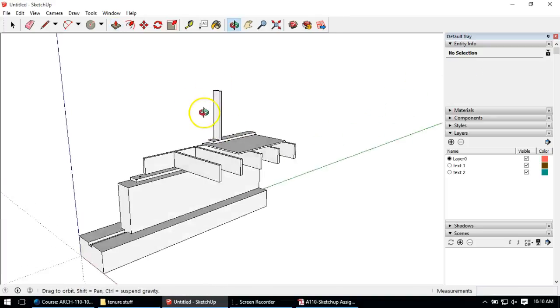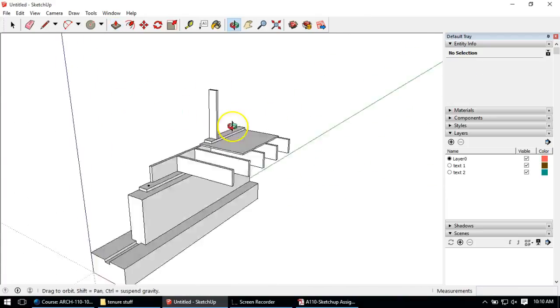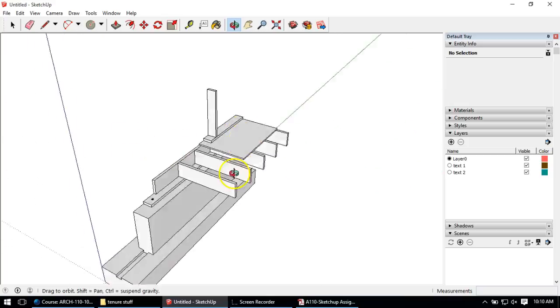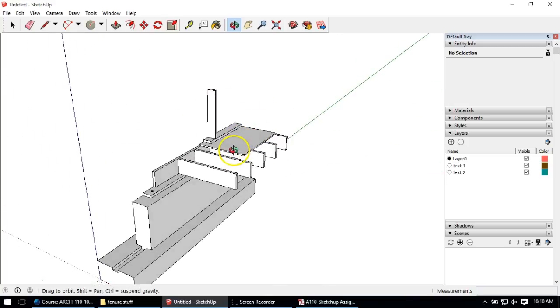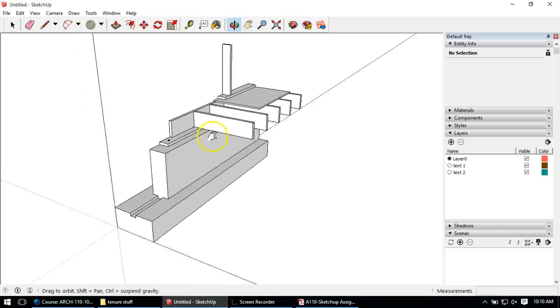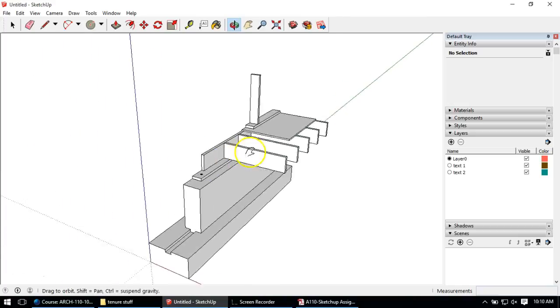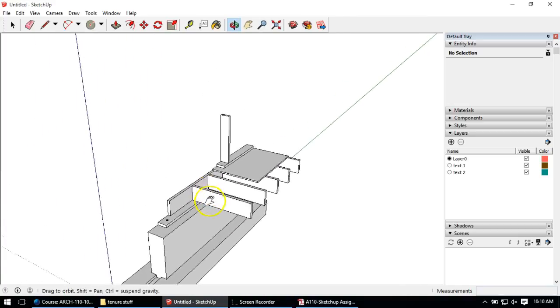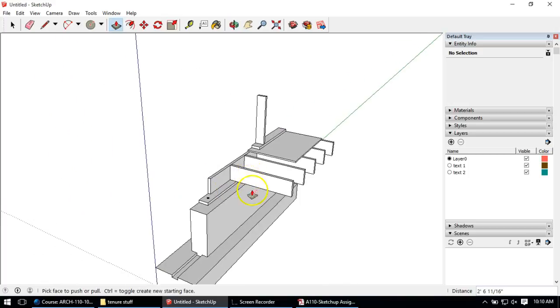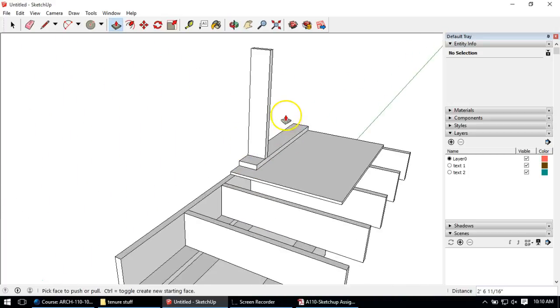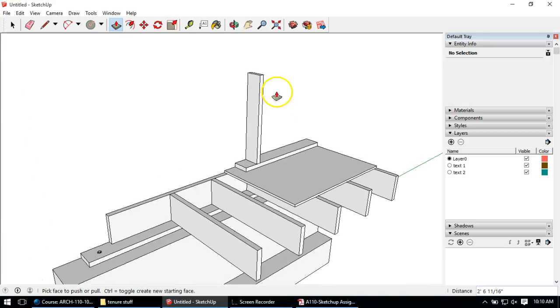And by the way, if I just push on my scroll wheel, in case you didn't notice, that's rotate around, revolve. If I hold shift and push, it's pan on my scroll wheel. Pushing and holding on my scroll wheel down, and holding shift, that's pan. And then to zoom in and out is push forward and backward. So similar to AutoCAD, but not identical.